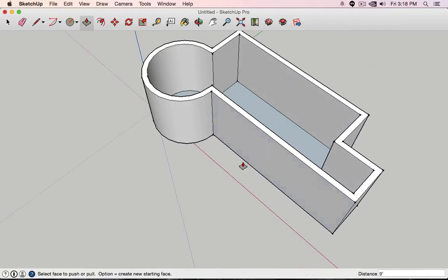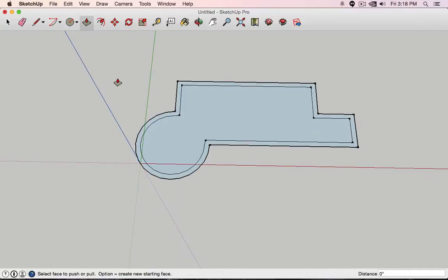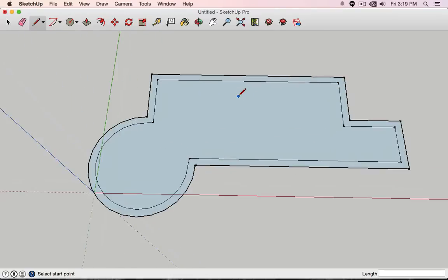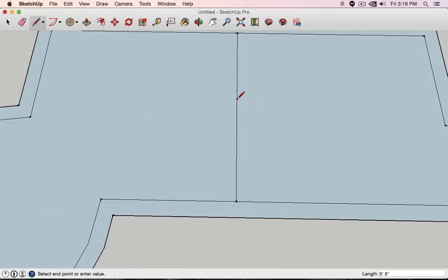Let's say you would like to add a wall in between. So what I would suggest anyway, before you create walls, try to have this all drawn actually on your floor plan. So let's say here from the midpoint to the midpoint we make a line. And now I would like to have another line 8 inches away. Little tip, go to somewhere perpendicular, type in an 8-inch line. I think I typed in 8 feet, 8 inch there.